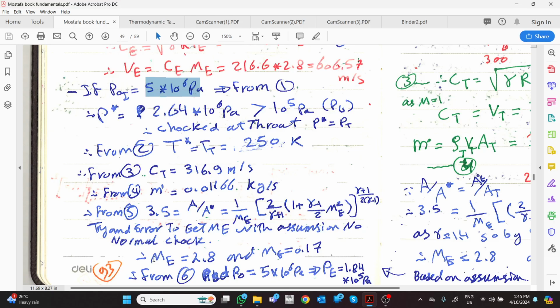Then Mach, to write the calculation of Mach at exit. Of course, it will become the same number. Why does it become the same number? Because the area-Mach formula is a definition of A over A star. That's it, nothing else. A over A star and nothing else except Mach. So yes, it must be the same Mach number.